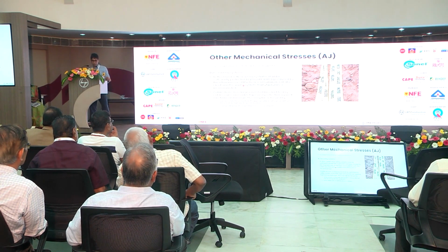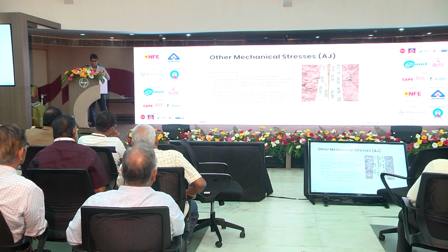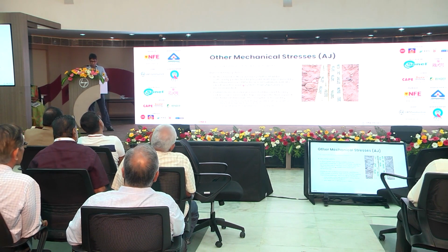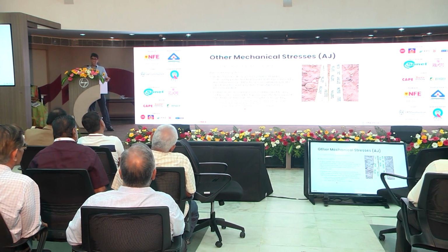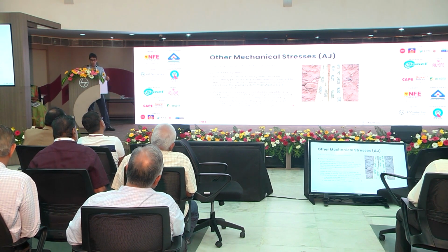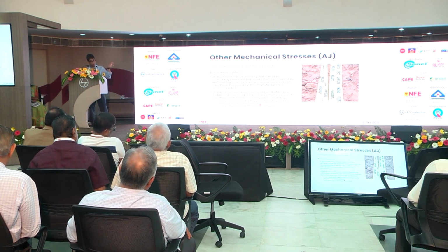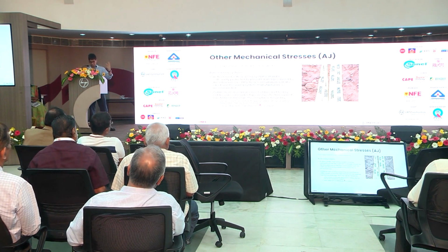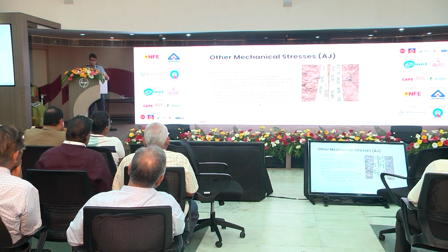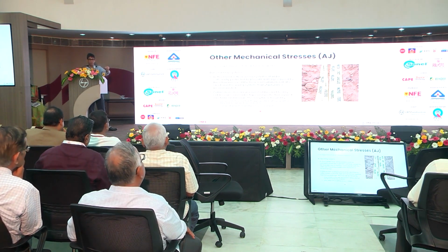Additionally, if you have underfloor systems in, say, a factory where you have a forklift operating, you need to make sure that it can withstand the impact of the forklift operating on top. You need to talk to the manufacturer about this. Additionally, if you're burying cables in soil, you need to use a conduit or duct with an appropriate IP rating, and the enclosure of the duct or conduit needs to be able to act as a protective conductor, just like an armored cable, or you may use an armored cable instead. This is to provide fault protection.